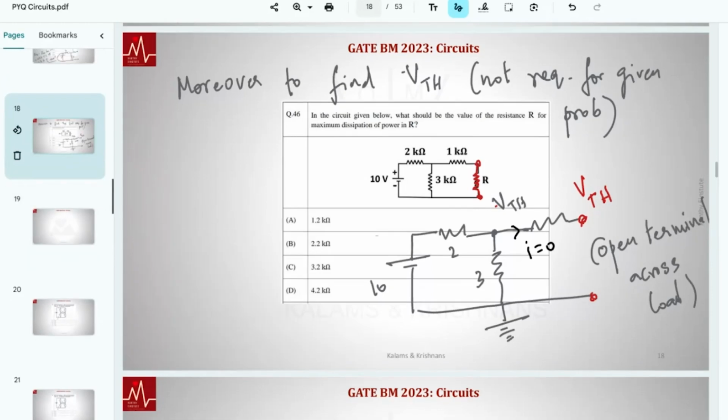Let's just look at an example of finding VThevenin. We'll wind up. How do you find VThevenin at this stage? Fairly easy. I hope someone answers this. Notice the voltage across this terminal. If I ground it, these two are the same, right? No current flows in that resistance. So what is the voltage here? That's what we want. You can write it down. VThevenin is the voltage here.